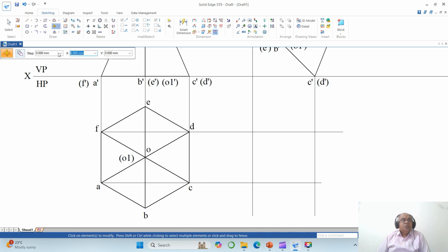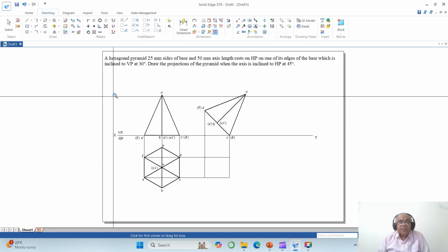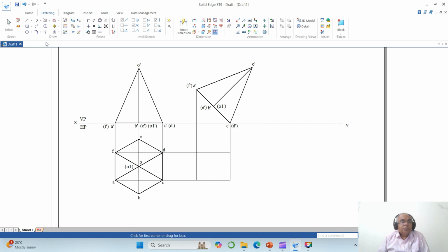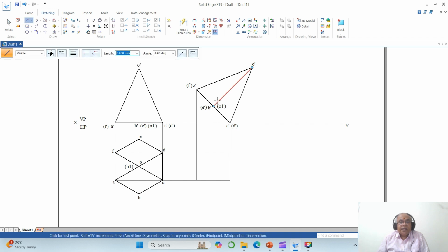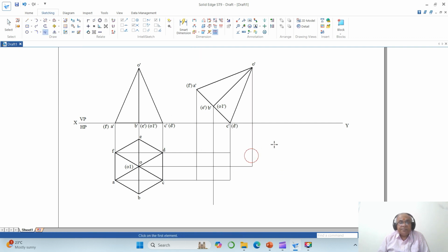Okay. Now we go for a trim corner between these two and also between these two and you check for a trim command using this. Once you do that, now we need to come down to a line command, draw a line from end point. Similarly from here. Okay. Now we go for the line command, draw a line from intersection. Similarly go for a trim command, trim corner between these two.